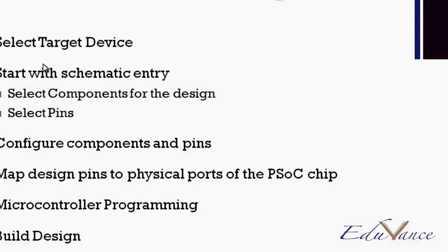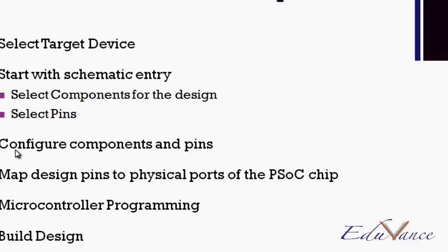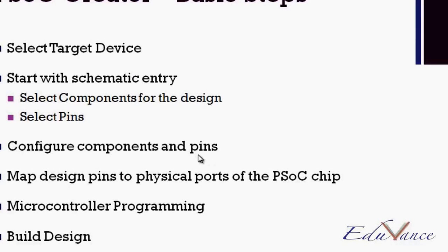So we finished steps 1, 2, and 3. We've configured the components and pins. Here we don't have any components. In lab number 3, we will have components, but we did configure the pins. Now we need to map the design pins to a physical port or pin on the PSoC chip. So let's see what we have to do there.